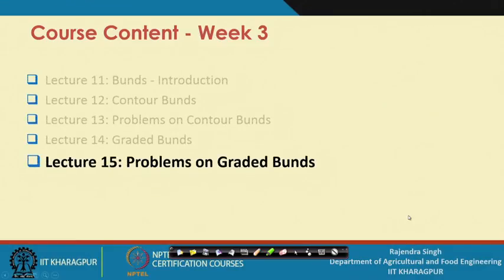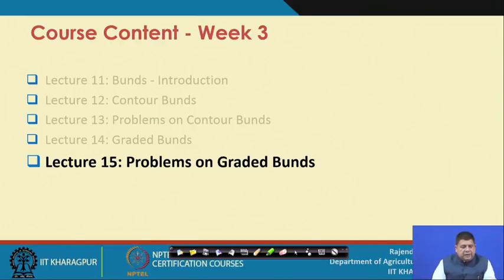Just to give you an idea of the course content which we have gone through in this particular week, we started this week with lecture 11 where we introduced bunds. Then in lecture 12 we went through contour bunds, that is design parameters, design principles, design considerations. In lecture 13 we applied those design considerations to solving some problems dealing with the design of contour bunds. In the previous lecture, that is lecture 14, we covered graded bunds, and today we will be solving problems on graded bunds.